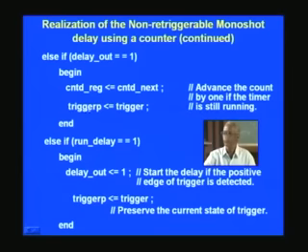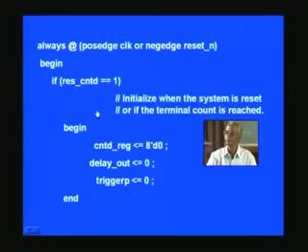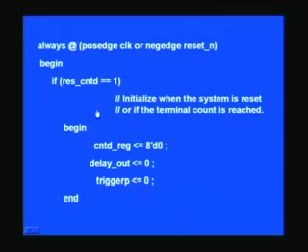So top priority is always put first, because naturally it is the reset which is very important, and we had to take a decision not to give priority to the advancing of the counter itself, and that is why this is a priority encoder. Wherever you have a priority encoder to be implemented, such as in bus arbitration in multiprocessor systems, you can use this way of coding.